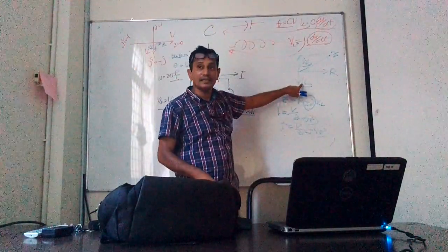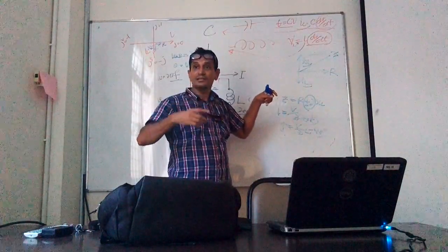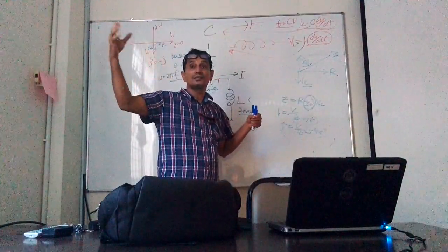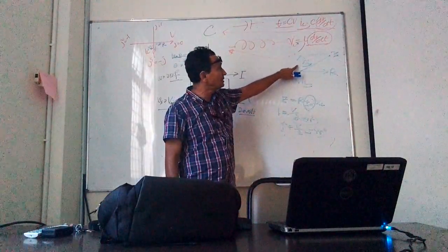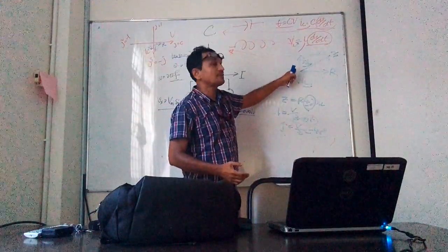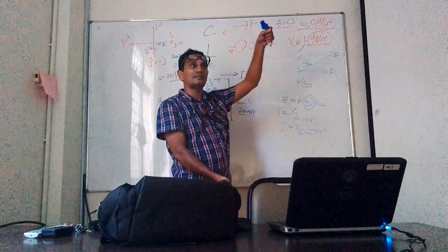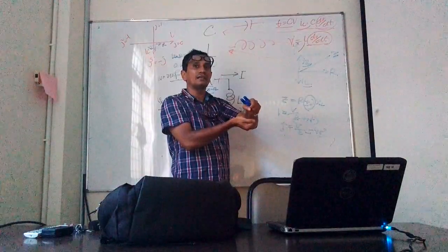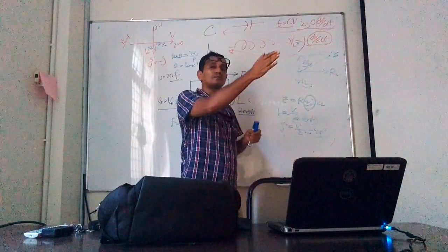So there will be current lagging. Then for the lagging current, to supply extra power from the supply system, they will charge extra, because extra current flow actually makes extra loss, heating loss in the system, in the line. So how to fix it? Then we have to put in a capacitor bank. That capacitor bank will make the capacitive reactance higher. So the adjustment of the inductive reactance and capacitive reactance can minimize the current leading or lagging, yeah? That eventually makes a resistive current. That means the same direction of voltage and current.